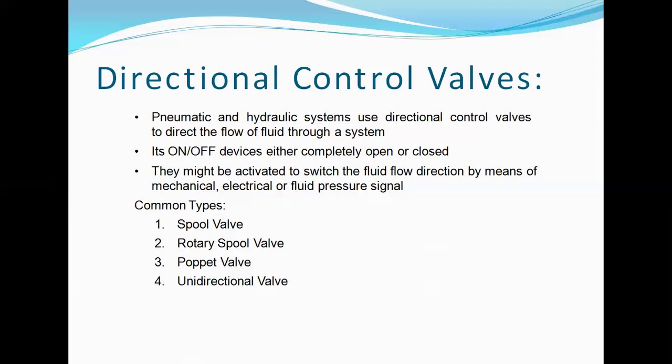So here, to guide the pressurized fluids, the directional control valves act as controllers and play a major role in moving the actuators towards the forward stroke or else the return stroke. So the on and off conditions are completely necessary for both strategies of the systems, either the open loop or the closed loop.